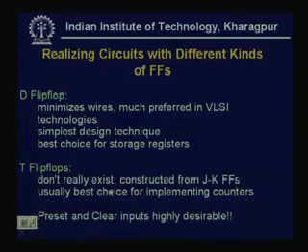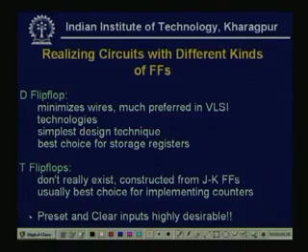Now, the simple D flip flop. It minimizes wiring, because we have seen that it is the simplest kind, much preferred in VLSI technologies because it is very efficient and takes very little hardware. It is the simplest design technique and the best choice for storage registers. That means, for 1 bit storage, number 1 is the D flip flop.